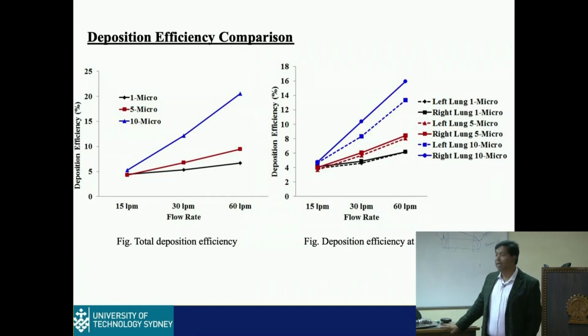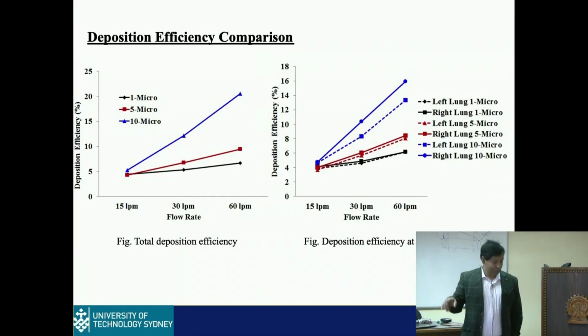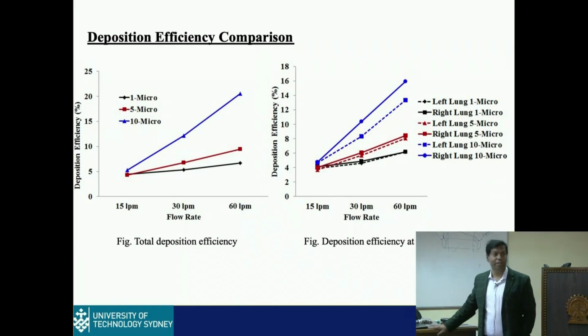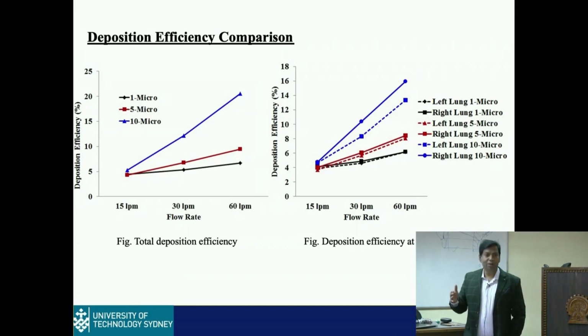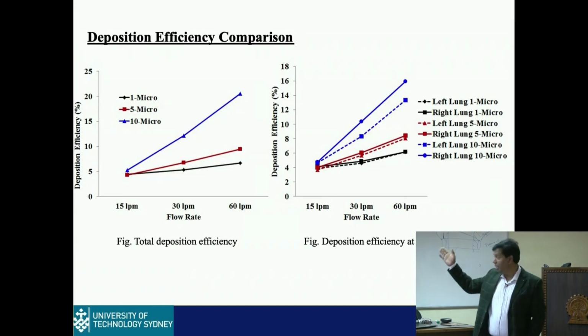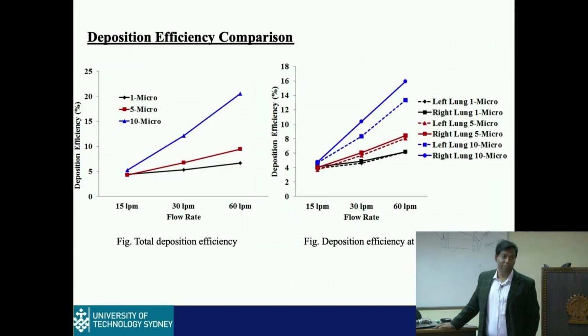But now you can use polydisperse. I'll show you in the tutorial how you do that. You have to give the maximum and the minimum diameter. For example, maybe the minimum is 1 micrometer, maximum 10 micrometer, and then you have to specify how you want the distribution. Okay, it is a normal distribution. Then you give the middle value, the maximum. Maybe 5 micron has the most particles, or you can specify which one has the maximum number, maybe 8 or something. Then the curve will be like that. This way Fluent can automatically distribute the particles.